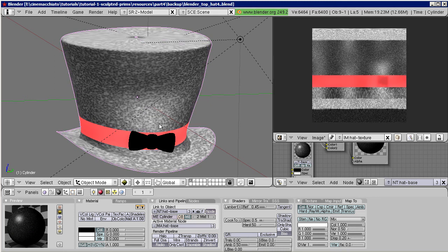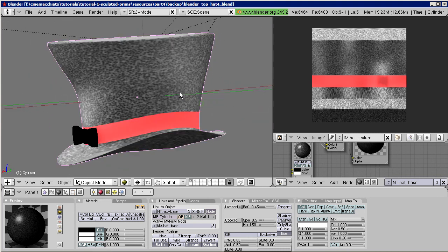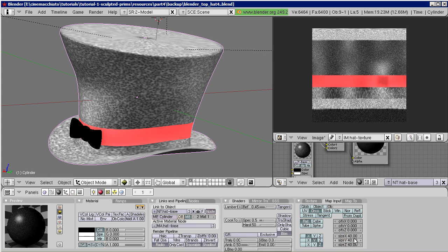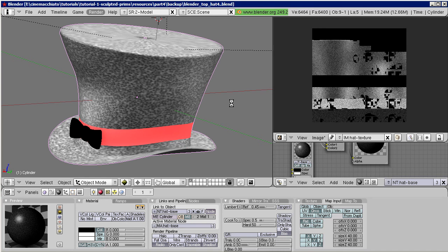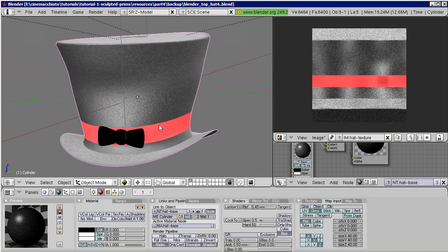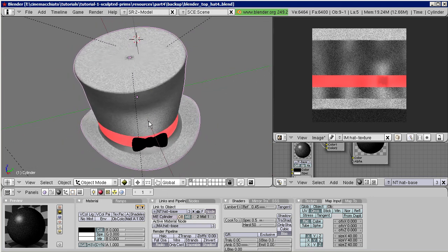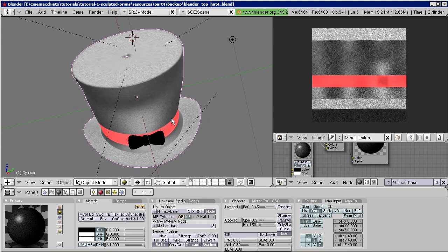The spot size is still much too big. So let us change that in the map input section. Change the size settings from 1 to 40 in all dimensions. Then bake again. Now the hat is almost like we want it, but it has become light gray. This was because we have chosen the secondary texture color to white. We could have used gray instead, and thus keep the hat darker, but we will do another much better trick.